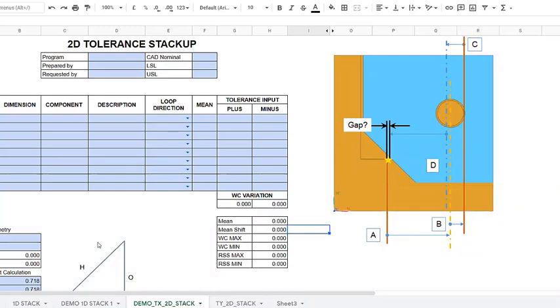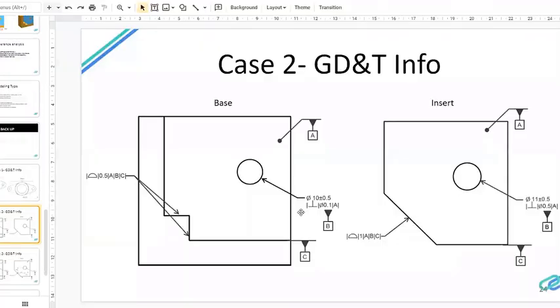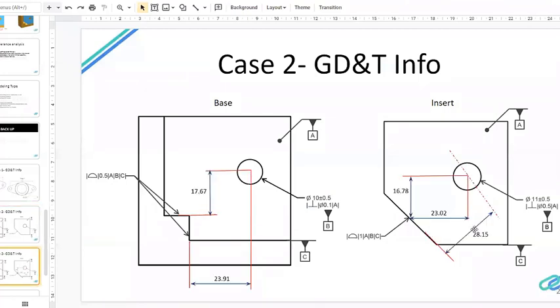For this drawing, we may not have all the dimensions that we are interested in for the stack, so I just prepared those dimensions. Let's take this, it's very simple. From the axis datum B, this vertical also. From nominal we have an angular surface of 28.15, but we need a tx and ty component of it. So we need to do a small trigonometric calculation to find the horizontal and vertical component, or simply we can measure the point in the CAD tool we are using.